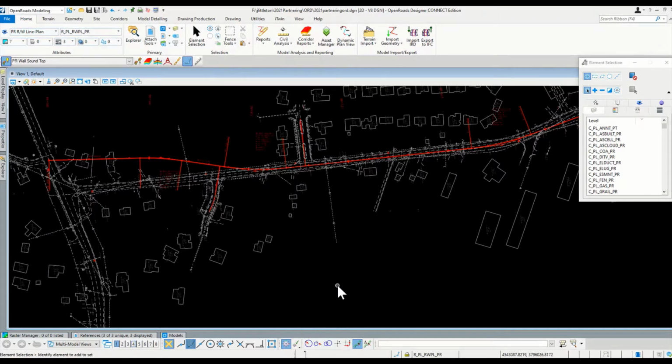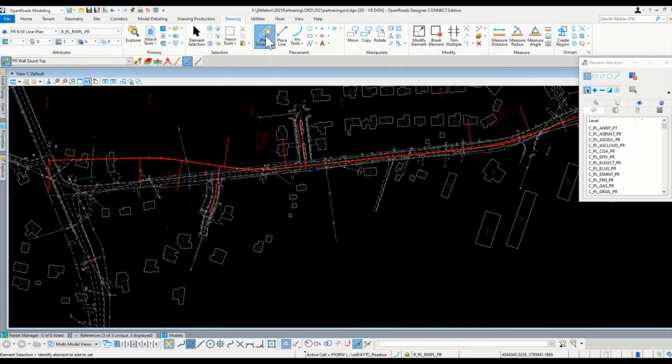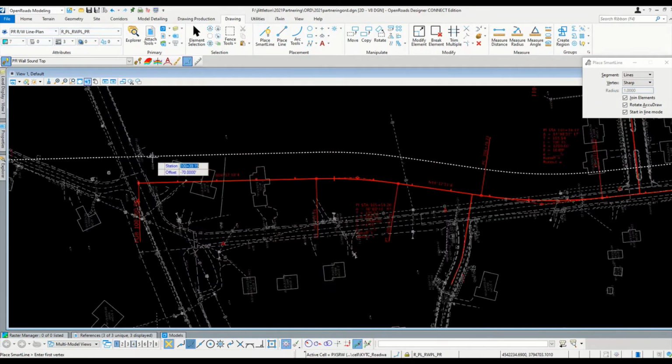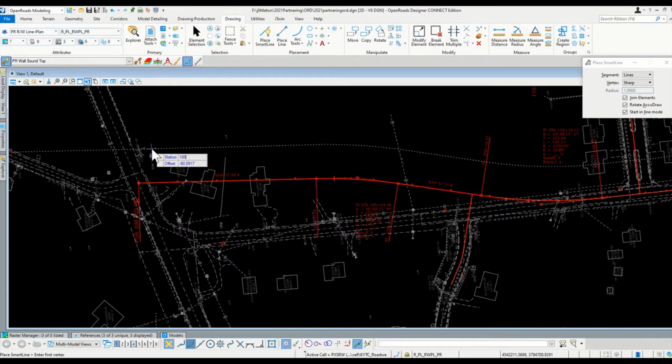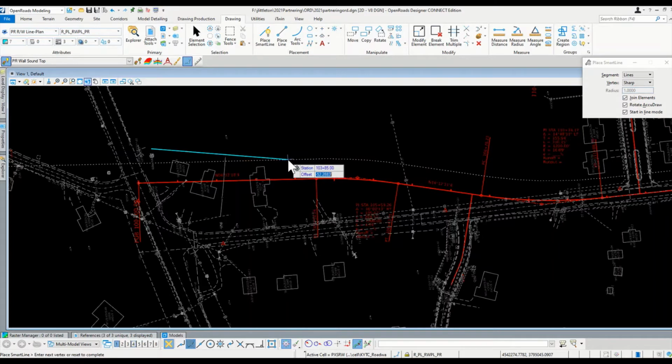But the first one, you'll notice that the tools when you're working in a plan view versus when you're working in a dynamic profile view actually change. So you have different tools available depending on where you're working. In plan view, the most powerful and most useful one in day-to-day work is the station and offset, and that does exactly what it says it does. Down here, station offset, if I'm laying out my right-of-way, I can say I want this to be at this particular station and this particular offset, and just go through and put those right-of-way breaks in there.